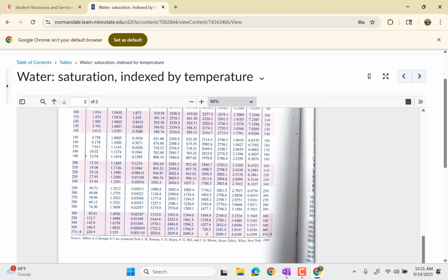But now look at the specific internal energy for liquid here and for vapor here. It's the same temperature and the same pressure, but there's a huge difference in the specific internal energy. You can think of that as the internal energy for a kilogram of the material. So we only had 419, I think these are kilojoules, of energy for that material when it's water about to start boiling. But by the time the whole thing is boiling, still at that same temperature and pressure, we've multiplied that by 6 or so.